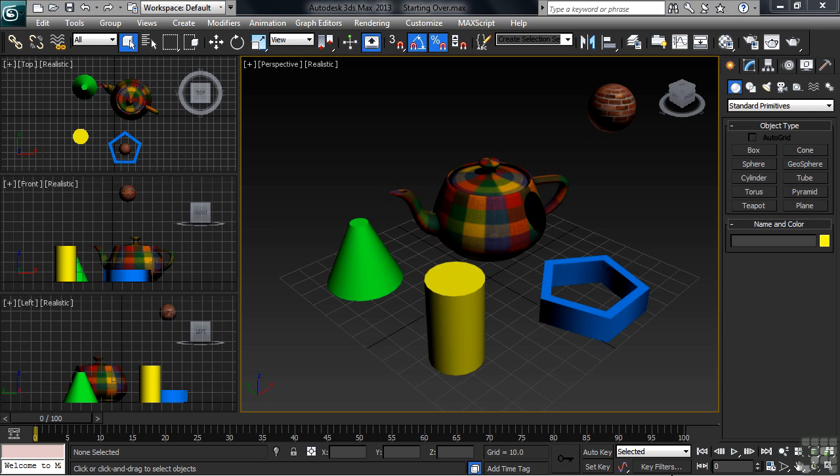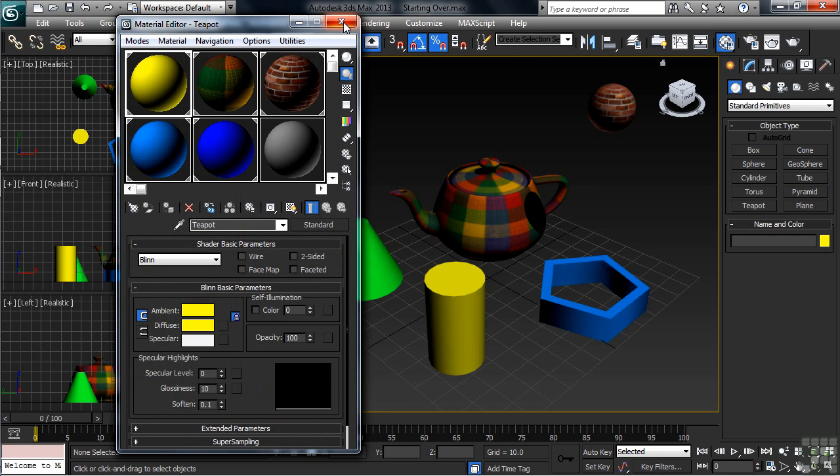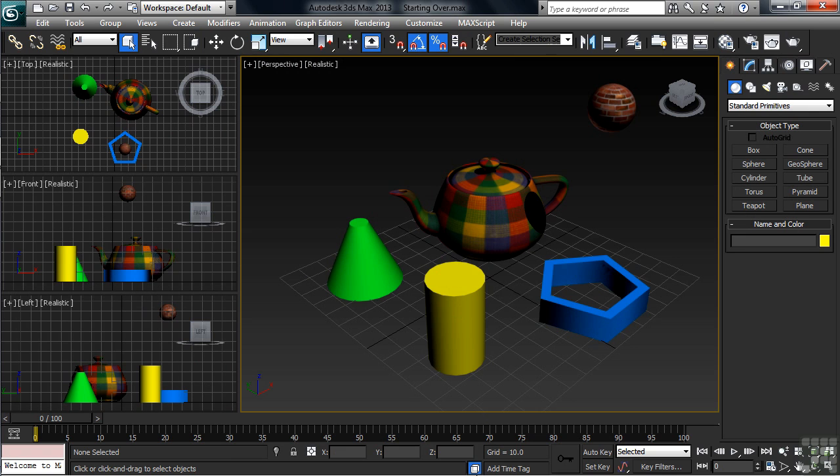Now we've carried over our objects in addition to holding on to our viewports, snaps, and skins. What was lost in the transition was our animation. Any and all keyframing that might have been done in the original scene has now been removed. You can verify that by scrubbing the timeline. So Keep Objects keeps your objects and any configuration settings. What it doesn't keep is any and all animation that you might have had built into the file. Now, be sure to keep that one in mind.